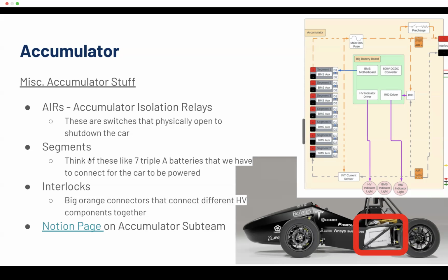But yeah, then those go to the BBB, which has the BMS motherboard on it. You can see how the daughter board daisy chain goes here, D1, D2, D1, D2. It goes through, and each segment is connecting to the next one. Any questions on battery segment architecture? If you want the stack up of how that looks assembled, go to the SN1 or the SN2 documentation. I think both of them have the same diagram.